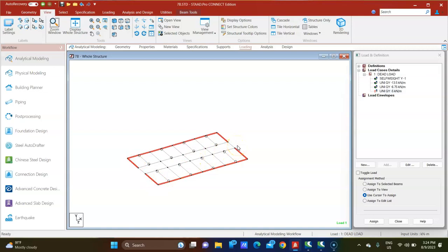On these two beams, this load will not be there because the staircase height is something different, right? Accordingly, whatever load will come, you will have to put it on these two beams, right? But here, this 5 kilonewton per meter load will be there. Fine. You see, you got it? I am not calculating that one. You see this one,